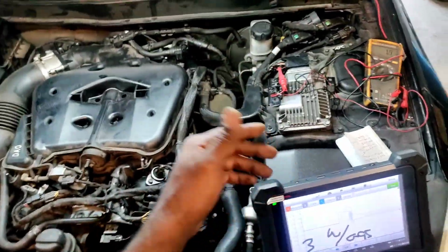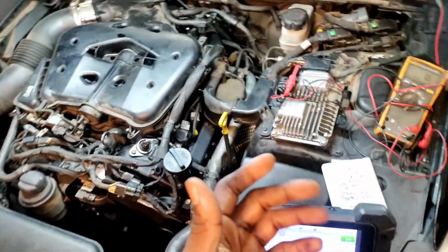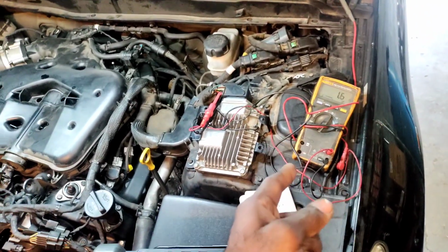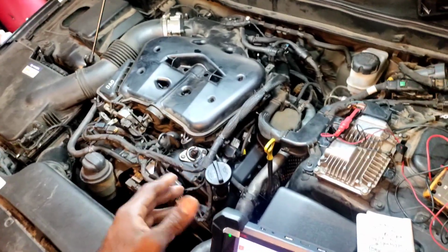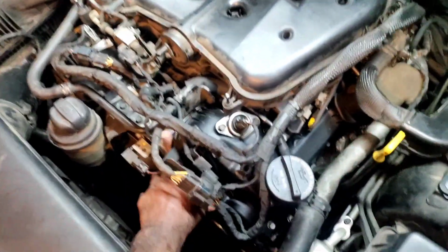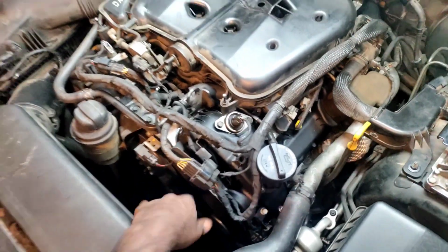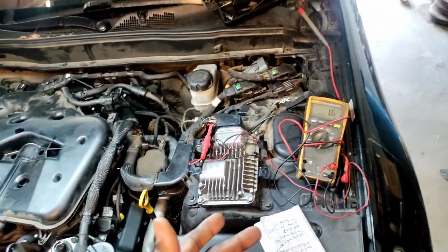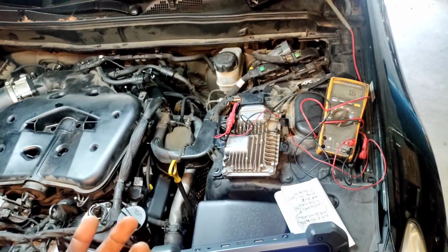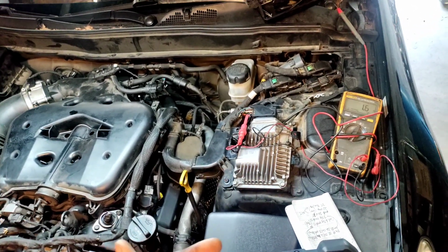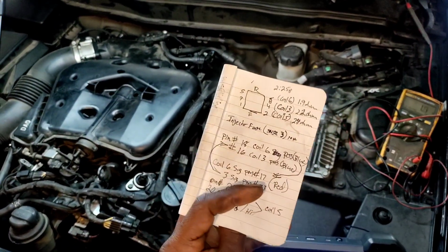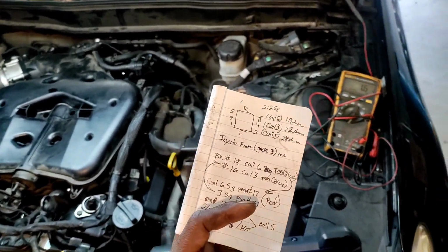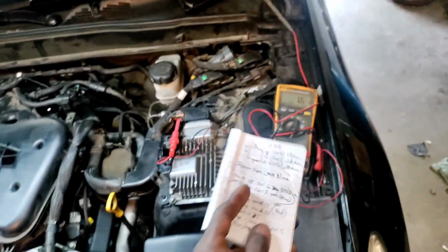Okay, let's move on. Today I wound up hooking up the ohm meter, got the temperature down, and I had a fan on the motor. I feel like it's about 100 degrees, 90 something, because it's warm. I can touch it and put my hands on it. Did another resistance check yesterday when it was about 190 degrees. It was around 2.2 ohms, 1.9 ohms. I'm on coil 3 right now.